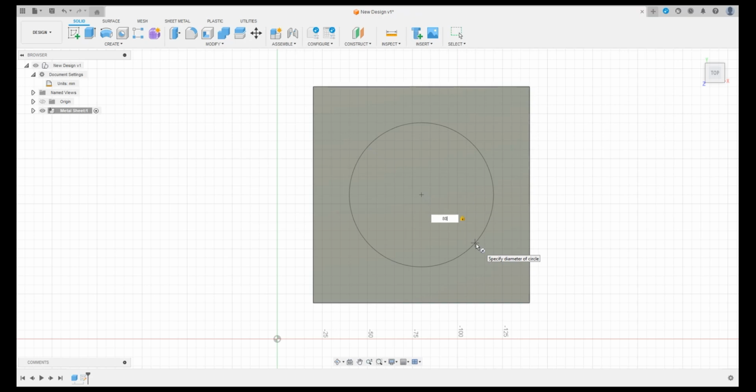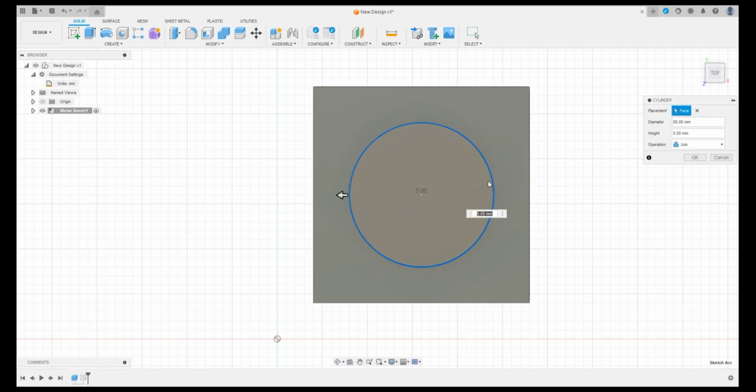We'll once again enter a value for the dimension of our shape, only this time it will determine the diameter of the cylinder. After we finalize the diameter, we'll decide on the height as well. If the placement of the cylinder looks good, then we can cut it out right now by making our shape -10 millimeters. However, if we want to adjust the placement, then we can go to Operation and New Body.